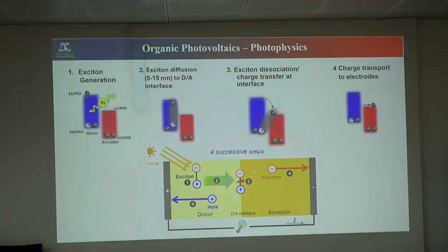Because everything is a bulk heterojunction, the electron can be recombined and lost if it encounters holes. In the donor phase also, we can't say the path is free. A lot of acceptor and donor material is still there, and the carrier can encounter another n-type material and recombine. Only the holes or electrons that avoid all those obstacles can be extracted. Most of the rest get recombined. Only those that travel the pathway successfully can be collected. So there is loss happening.